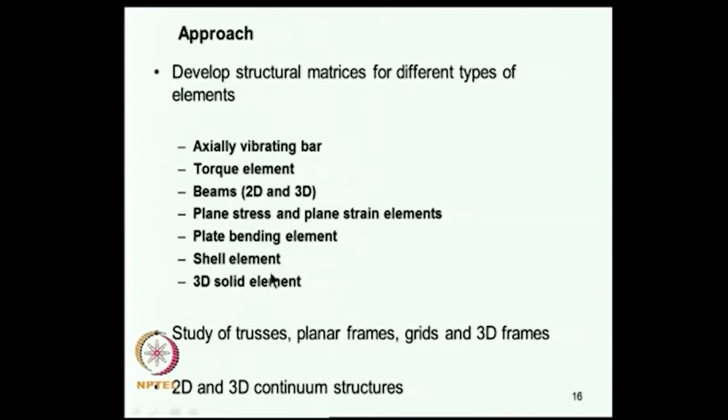For each of these we will characterize the behavior of a single element, and then we will address the question of how to assemble the formulations at element level and study structures such as trusses, planar frames, grids and 3D frames, and also certain 2 dimensional and 3 dimensional continuum structures. So, this is the broad outline of at least the next few lectures.